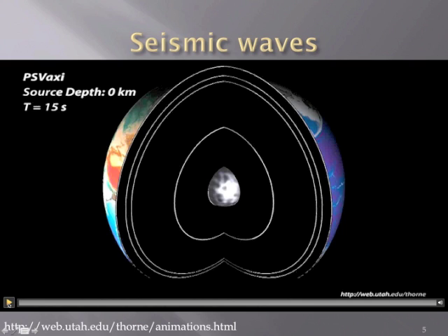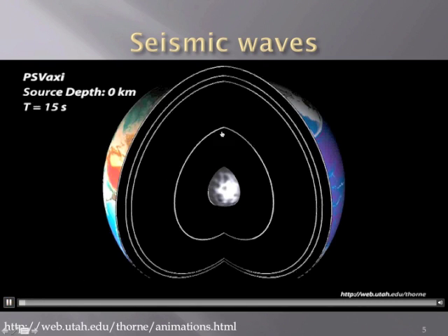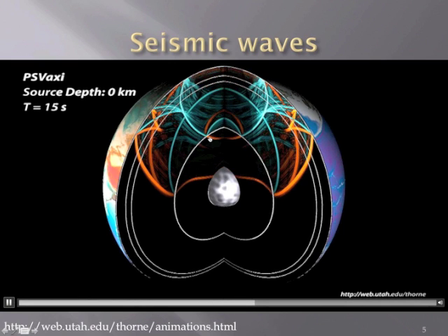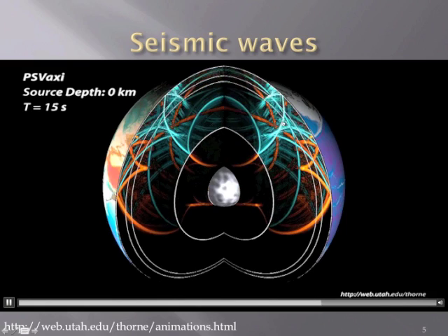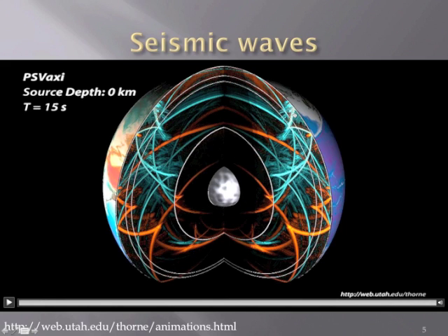And here I'm just going to show an animation, to get a big picture of how those waves propagate. So after an earthquake, for example, that happened near the surface, you have P wave going down, S wave going down. P wave is red, S wave is green color, and then you also have this surface wave propagating near the surface, which is much slower than the P wave and S waves. And so this surface wave, because it's very sensitive to shallow structure, it's particularly nice to use this surface wave to study near surface features.